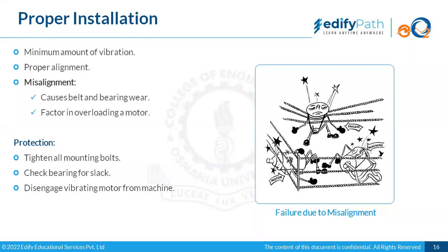So bearings, in a smaller motor, are not a big issue. But if you talk about alternators, bigger machines which run at 3000 RPM, bearing protection and bearing cooling are a separate process in the motor and in the generator. So we have to take care, and proper protection has to be ensured. That could only be ensured when we have a proper alignment.